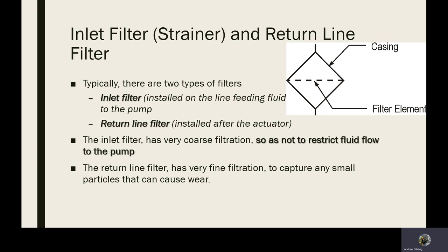Now, on larger hydraulic systems, in the wind turbine world, we have quite large transmissions, hydraulic transmissions. The one I'm thinking of, D-Wind, is basically a torque converter, very much hydrostatic drive, and the hydrostatic drive output is to the generator, and the input is from the main bearing or from the mechanical gearbox. Its job is to smooth out all of the bumps from the wind and the grid, and the fluid in the transmission does a wonderful job of it. The only problem is the oil must be kept super, super clean in order to do that work.